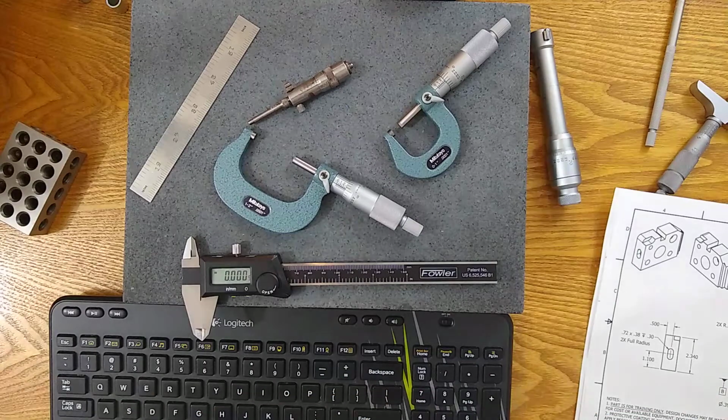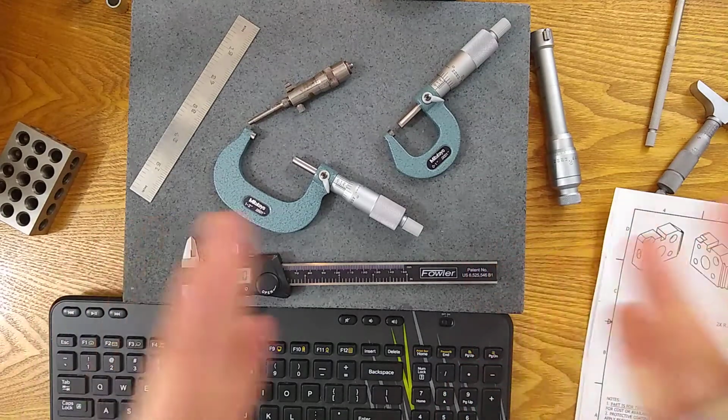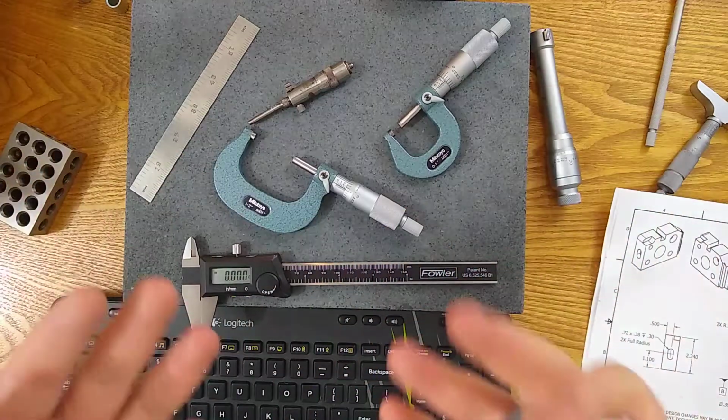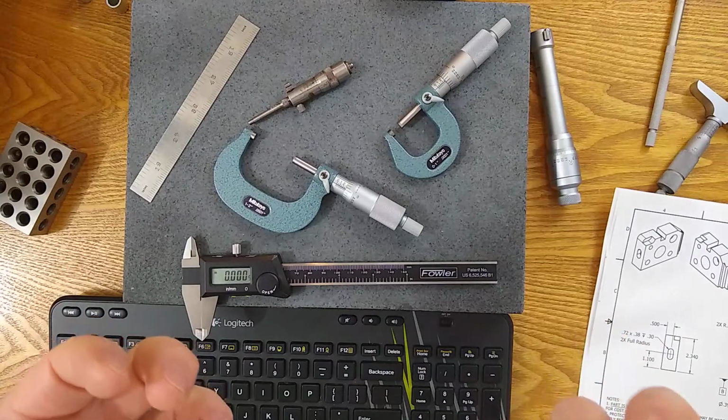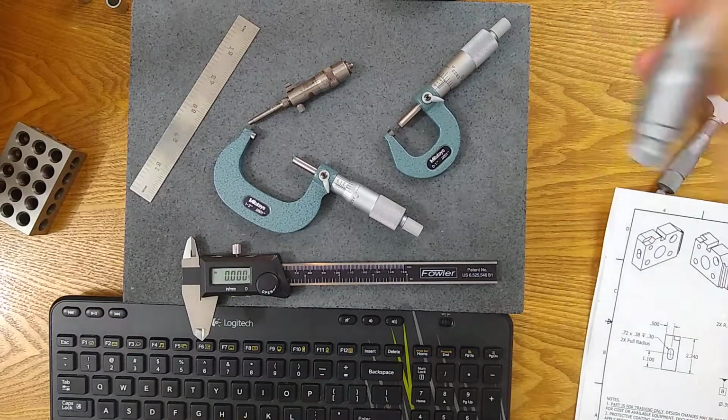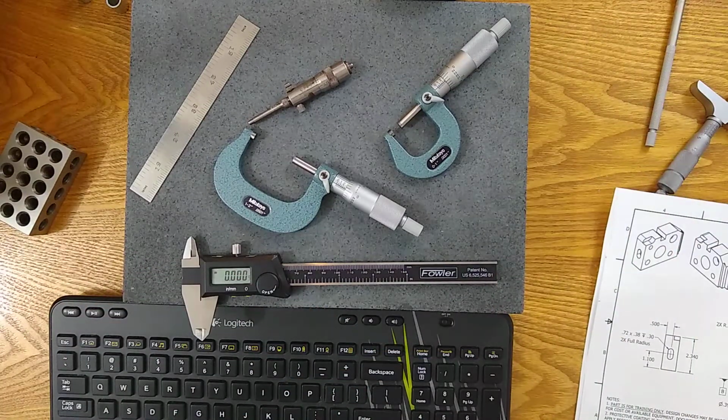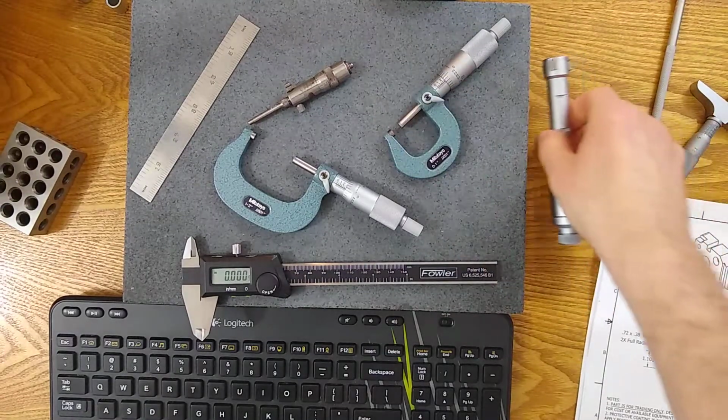Last one, consider your experience with both the part and the tools, and what tool combination optimizes your inspection. That's taking everything into account. That's factoring in your own experience. Like I said, sometimes I've been in situations where I should have used a more accurate gauge, but I didn't know how to use it. So I made a substitution. The dial bore gauge is an example where, when I wasn't so familiar with them, I might have used a hole mic, still pretty good accuracy, but doesn't reach the depth that the dial bore gauge does.